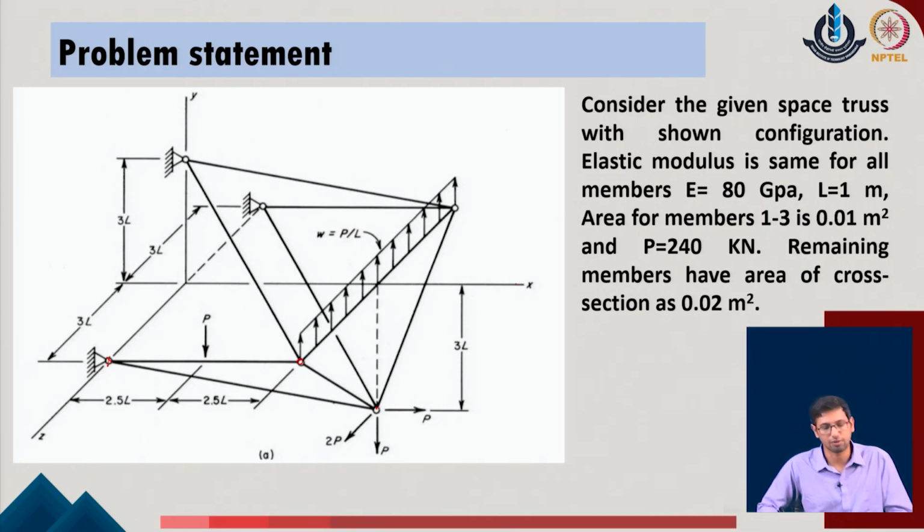Its coordinates are defined below the given axis, y equal to 0, and that is where the members are connected, say from this initial point to this given point. These members no longer remain within one given plane or a specific plane of x-y, y-z, or x-z of the given system. So as the orientation of the members can take up different planes of the given system, not necessarily a specific 2D plane, this is called a space truss, right.